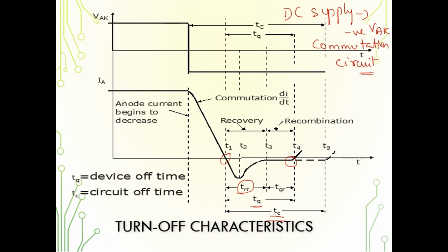We have seen the VI characteristics of a thyristor, and what happens to them if we vary the gate current. We have seen the turn on characteristics and the turn off characteristics of thyristors. We can make our thyristor conduct without the gate current provided our anode current is very large, and it has started to conduct on its own, that is, it has latched.